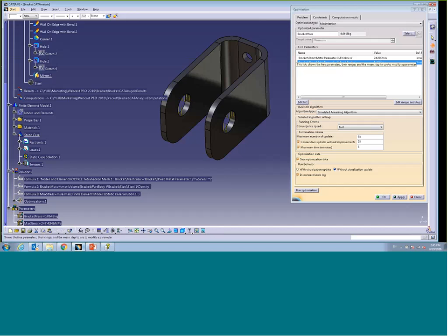The recommendation is at this point I can lock one of the parameters, for instance, thickness, and then optimize just the remaining parameter, like a bend radius. So this is something you have to do sometimes. I don't want to do it. We don't really have the time. Hopefully that kind of rounded off the presentation of optimization.